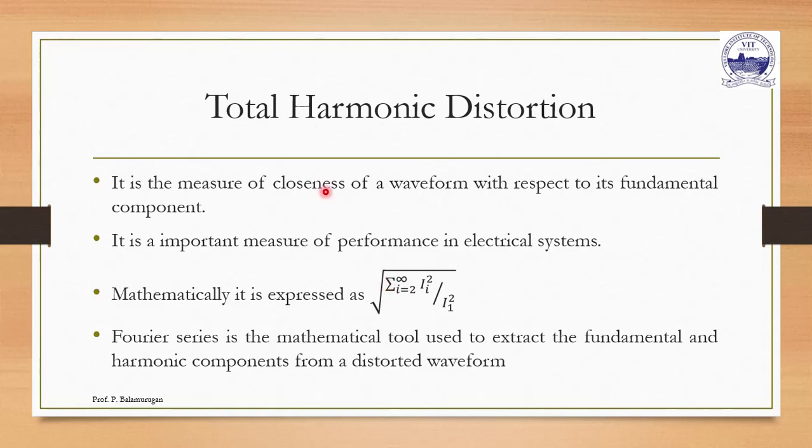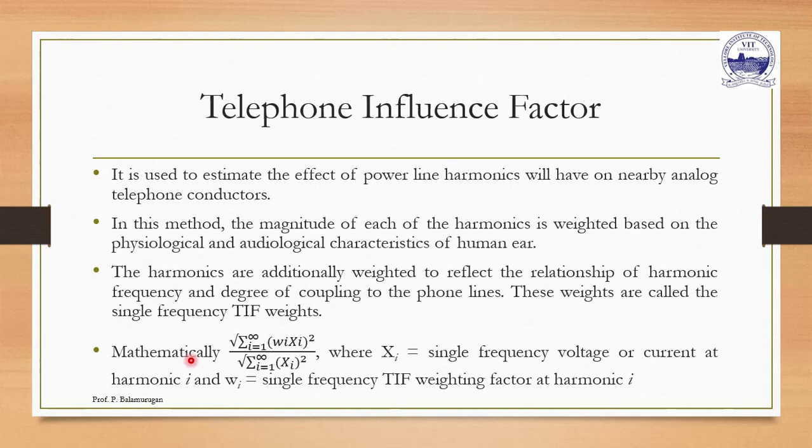And in order to evaluate the total harmonic distortion, the Fourier series is the mathematical tool to extract the fundamental and the harmonic components from a distorted waveform.